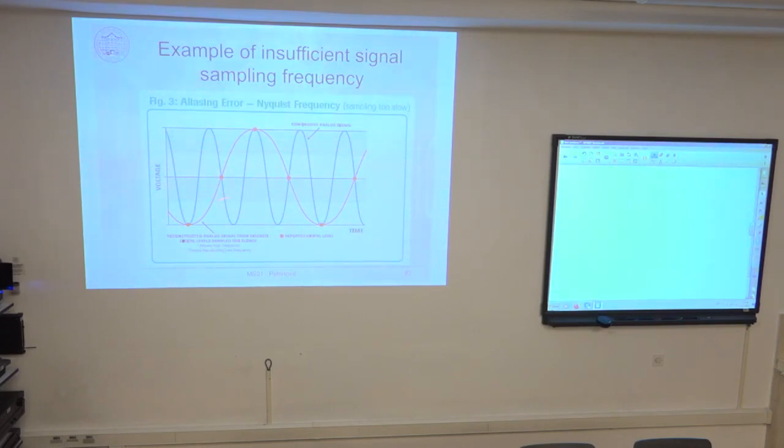So the signal represented by these samples is the red one. Because if the blue one is at the input, I could not distinguish later on whether it was red or blue. This sequence would give either, but the proper one is the red one, because the red one is satisfying the Shannon-Nyquist condition. The blue one is too high frequency. So its frequency is much higher than is allowed by the Shannon-Nyquist theorem. It is higher than half of the sampling rate.